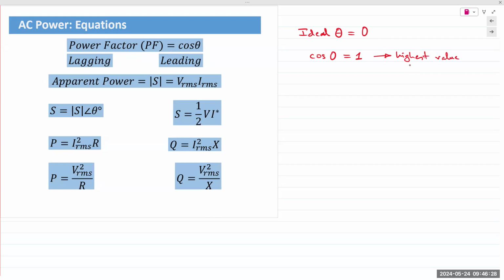If the capacitor supplies more energy, now your angle goes negative, right? If you require only 10 and you provide 11, now you're going below the real axis. So then it's a negative angle. The source still has to send energy. And so this is also labeled as a percentage or 100%. I think typically, let's take PG&E for example. I don't know the latest numbers, but I think they require a power factor of at least 90%.